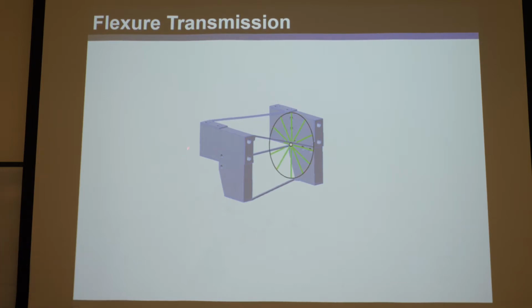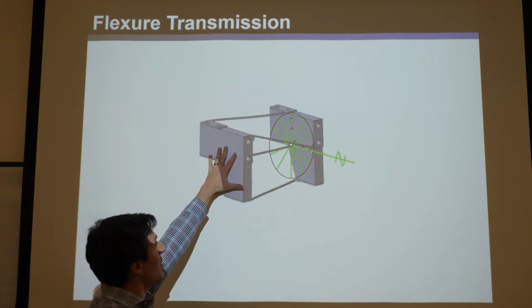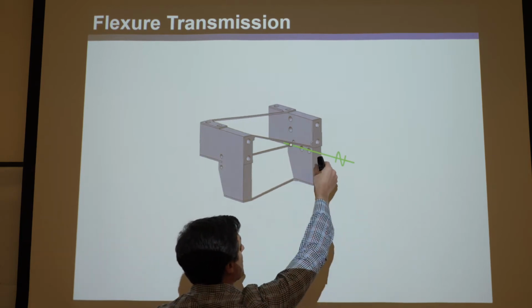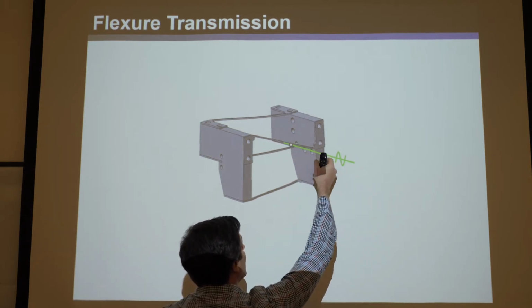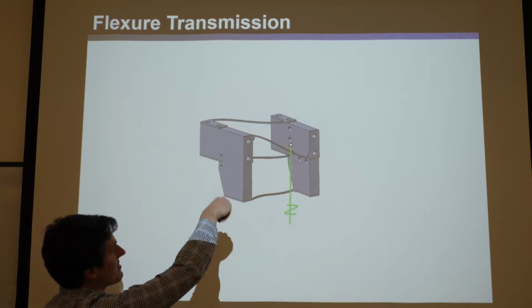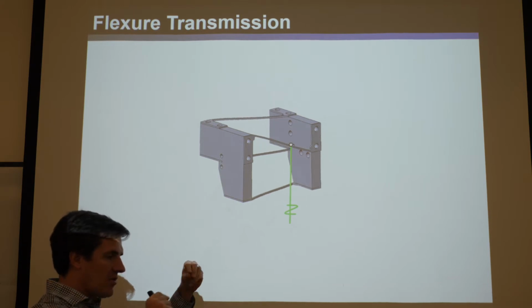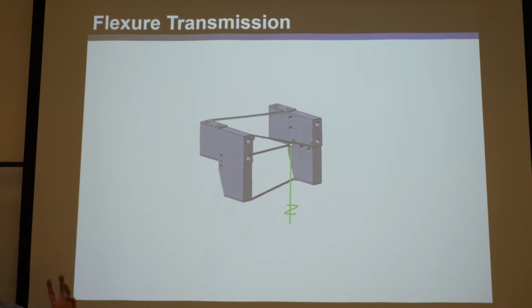And you'd find if you ground this, it achieves this disk of screws, which is pretty tough to visualize, but you can think of it, if I ground this and I push or pull along this axis, it will rotate with that coupled pitch. And then if I push along this axis, it'll rotate along that. And really, if I push along any of those axes, it will translate as it rotates around it, okay, with the same pitch. Okay, but how is this useful for what we're designing?